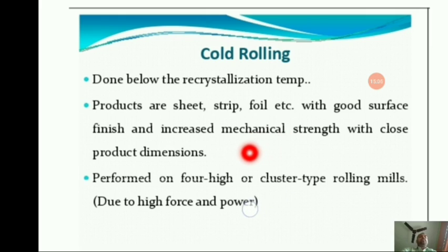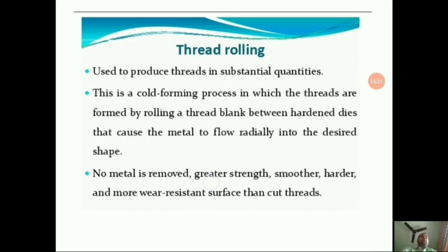As I earlier told you, strength and ductility increase in the rolling process, and because it is a cold rolling process, it will have close product dimensions as well. Now it is performed on 4 high or cluster type rolling mills due to high force and power.